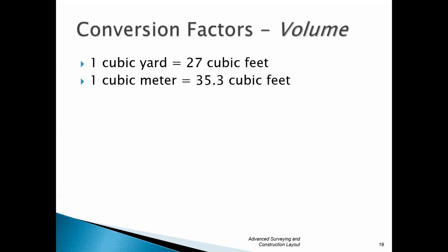And here's your conversion factors for volume. And this is an important one too. A lot of people screw this one up. The cubic yard is 27 cubic feet. A lot of people think 9 because cubed, 3 cubed, but that's not correct.